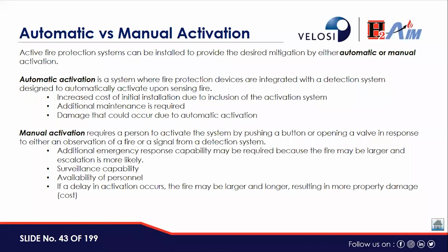Then what is manual activation? For automatic activation, there is a chance of spurious activation as well, so it can cause damage. Now, manual activation requires a person to activate the system by pushing a push button or opening a valve in response to either an observation of a fire or a signal from the detection system.